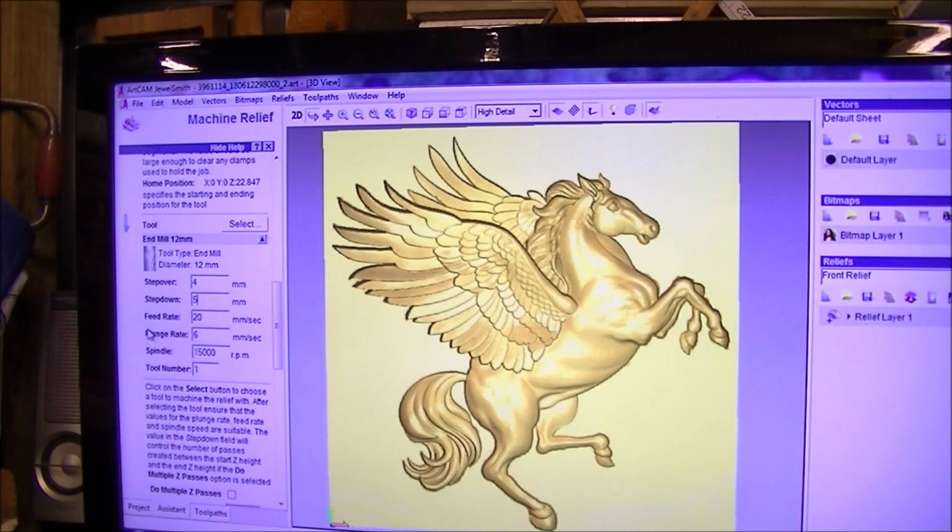It doesn't matter what the manufacturer says, when it comes down to actually machining, it just would not do it. Now it will, and more. So, just to prove a fact, I'll put this at 80, and I'll show you exactly how it'll cut. I'm using NC Studio as well, so I can actually run that at 120%.